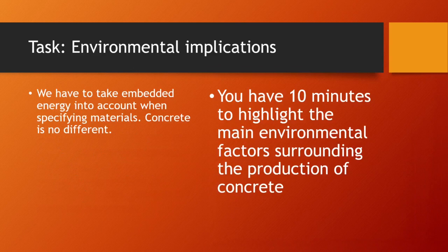So environmental implications. We have to take embedded energy into account. You have 10 minutes to highlight the main environmental factors surrounding the production of concrete. So take a look for about 10 minutes at what you find if you Google the environmental considerations of concrete. You've got the CO2 emissions, how much CO2 is emitted. And you'd be surprised, it's actually ton for ton. A ton of concrete curing on what we call Portland cement will release a ton of CO2. That's absolutely huge.